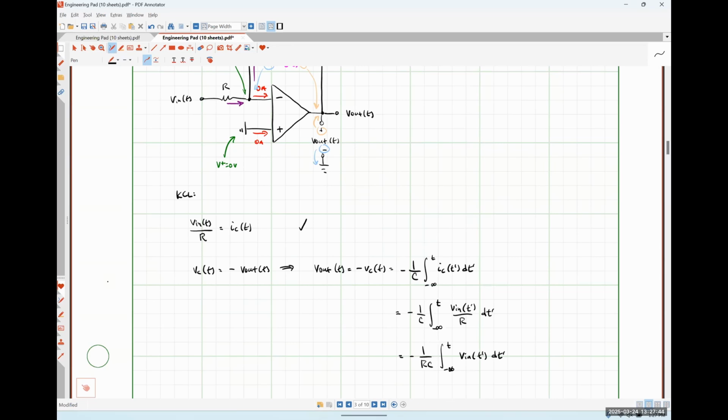So when you look at some of your different design projects, prompts particularly, these guys can be rather useful, right? So let's say, for example, if I wanted to convert a square wave into a triangular wave, I could use an integrator to do that, because the integral of a constant function is going to look like a line that's increasing at a constant slope. So integrators convert my square waves into triangular waves or sawtooth waves, stuff like that.